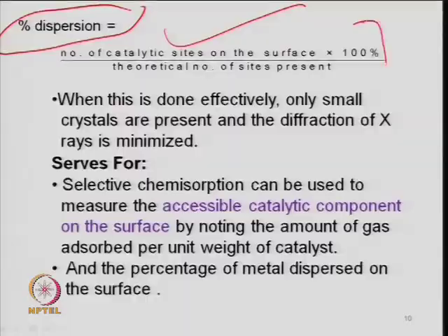So, instead of having 10 weight % of platinum, try to have 0.5% of platinum with more than 90% dispersion, or more than 70% dispersion. That should be your target, to get good efficiency from the small concentration which is used, and every site should be active for the catalytic reaction. So, dispersion becomes very important, and this is based on the turnover frequency also.